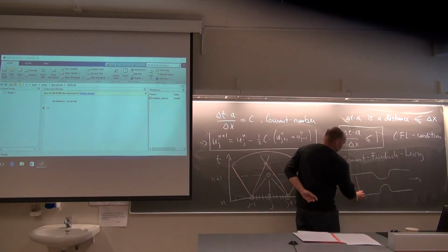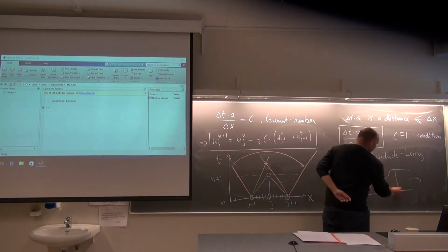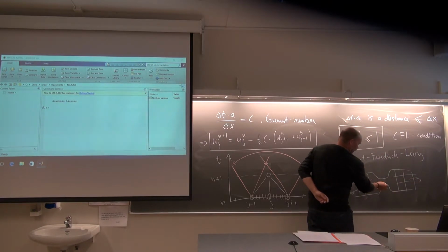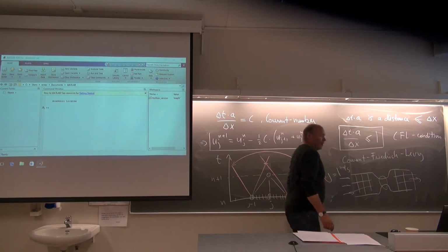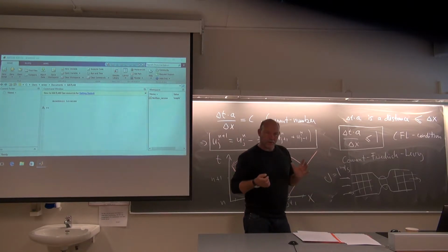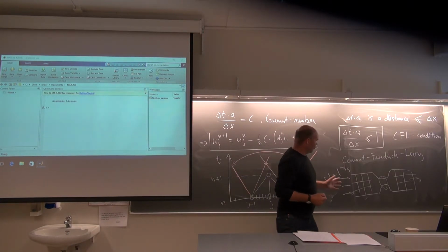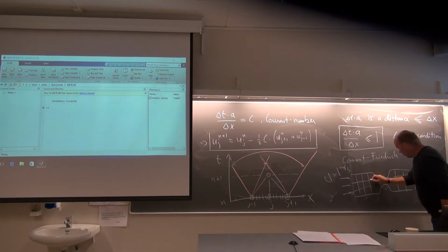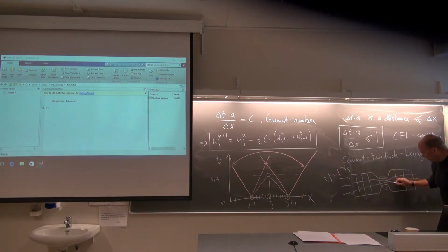So here we can use quite large meshes, and also here. But in this region here, a lot of things is going to happen. You will have a quite speed up of the flow. It's a very narrow opening, so the velocity here is going to be big and sharp gradients. So we are going to use a lot of cells in this tiny little region here.